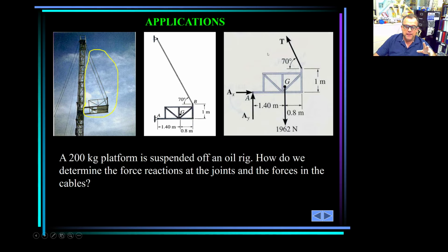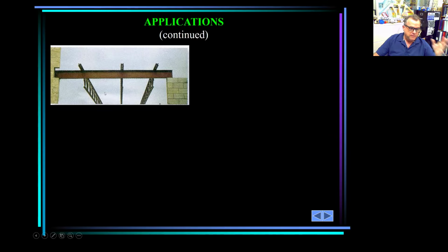And once you have that, then you proceed and you can calculate the unknown forces that are keeping that in equilibrium. And now you realize, in this other example here, you have that beam, that girder over there with 3 beams over there. That girder basically is just resting at this point, and this other point here somehow is resting, and it's not possible to slide in this direction. So if I have to think, I can say, oh, this wall is providing a reaction, a force that is coming in this way like that, and that force is avoiding this whole thing